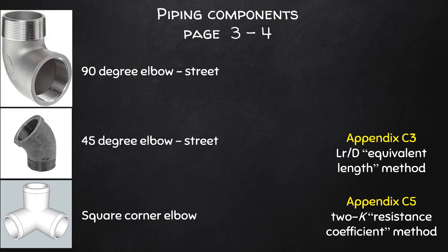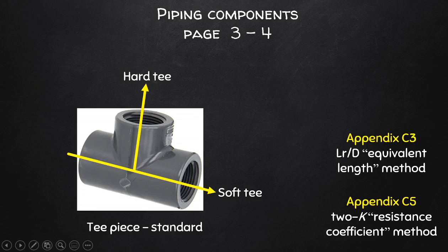We also have what you call 90 as well as 45-degree street elbows that have both female and male threading at their ends, where the male parts screw themselves into the female orifices to complete the union. There are also three ways as well, which join three pipes into a corner, usually 90 degrees in geometry. And speaking of 90 degrees, we also have things like T-joints.